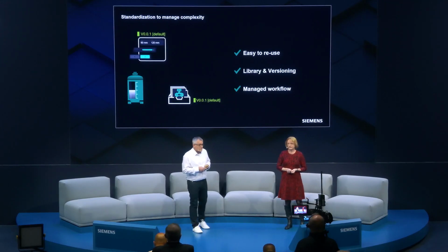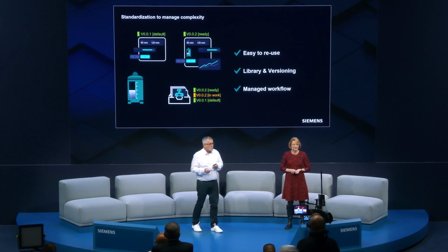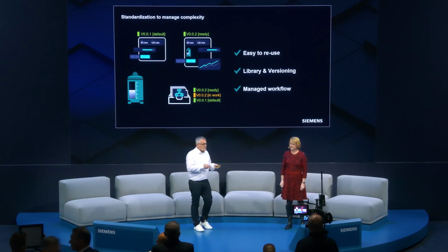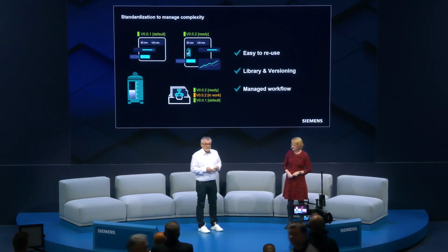Consistency over those platforms is definitely an enormous advantage during engineering. But integrators have to deal with multiple versions and devices, and how can they ever manage this complexity? The best way to manage complexity, of course, is standardization. And this is one real strength of WinCC Unified version 18. First, we start, for example, with the graphical elements, in our words, faceplates. Faceplates are reusable elements which can be a typical single screen element like a tank or a motor, but also an entire screen to operate this tank. Of course, including dynamization.